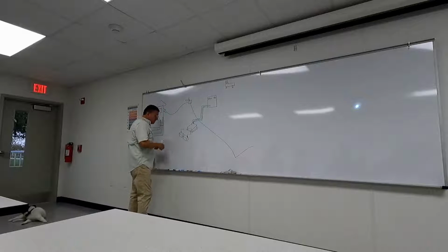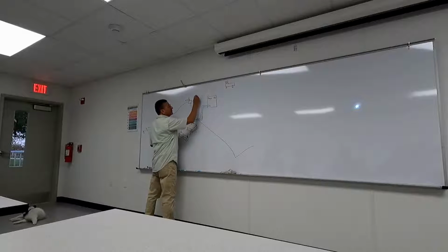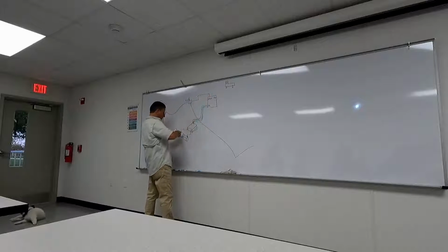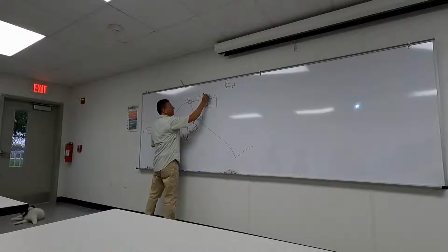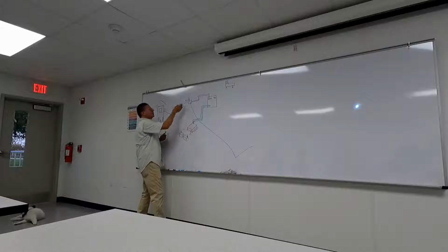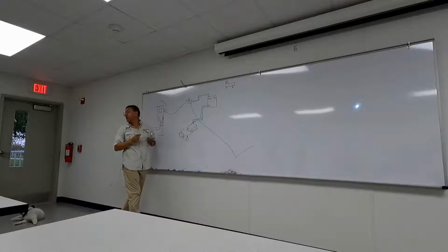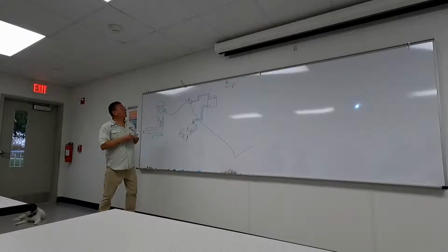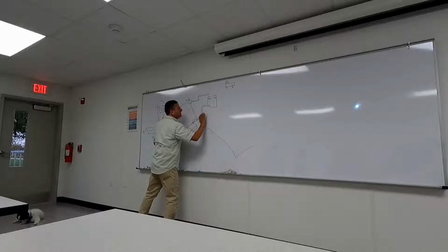Okay, and the same for the shore power. This is single phase. This is the first connection. Wait, Mr. Lopez, the ground doesn't go on the battery switch? Yeah, it's from the body of the inverter or the body of the generator or the body of the transformer. But does it go to the switch? It doesn't go to a switch. Sorry, no, sorry. This is only to verify if you pay attention.